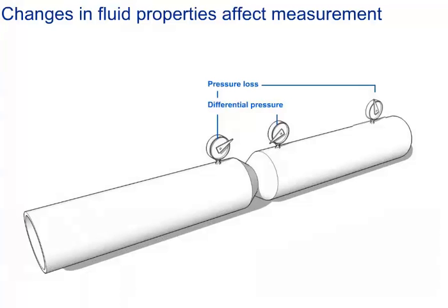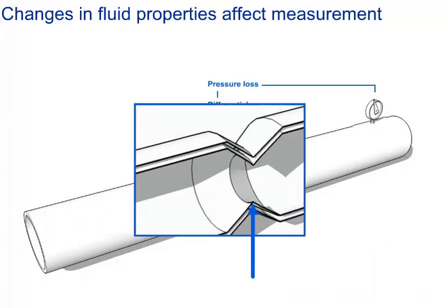As pressure loss depends on the restriction shape, the internal profile of the meter, as well as on the pipe-to-restriction ratio of the primary device, it can be reduced to a minimum by the selection of the appropriate DP metering technology.